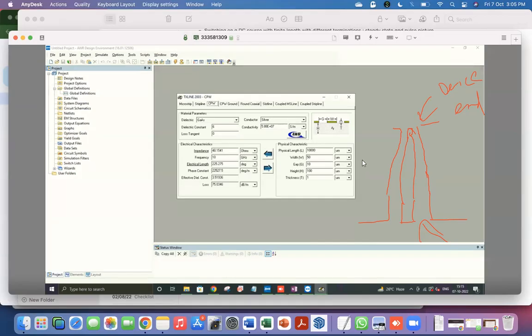Right, yeah. So this was CPW and CPW ground. So the rest, all these things are the same. Again, for both CPW and CPW ground, the effective dielectric constant is different than the true dielectric constant. That's just because now you have field lines present in the air, right? There is another kind of transmission line which is not used that much, but it's useful to know.